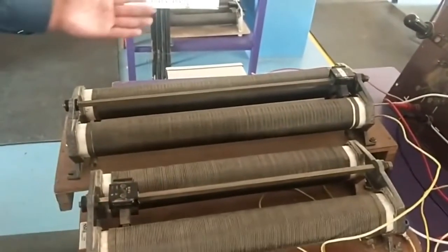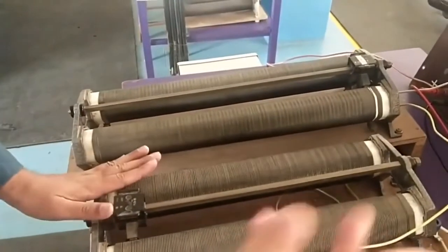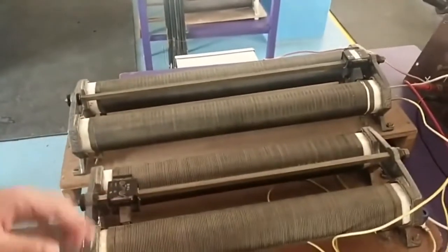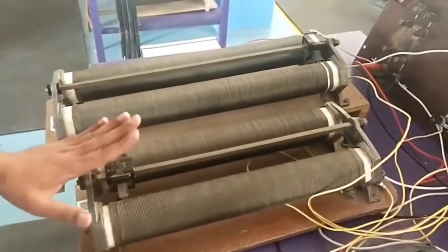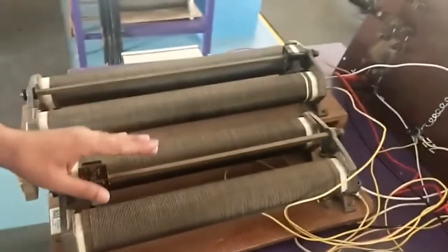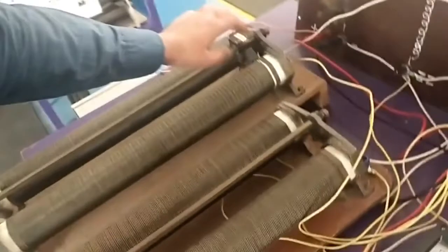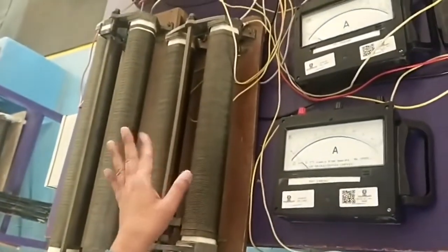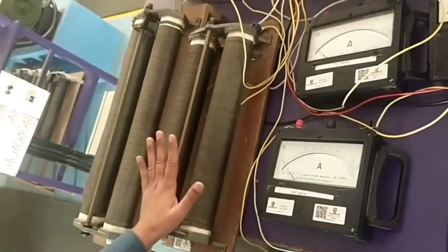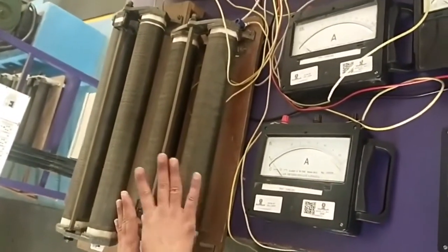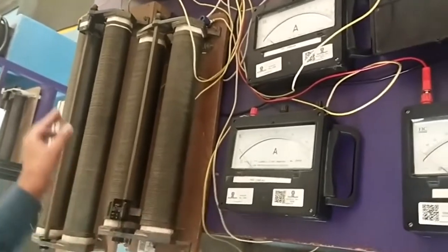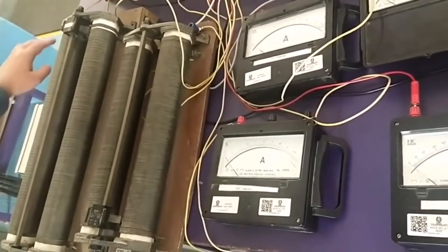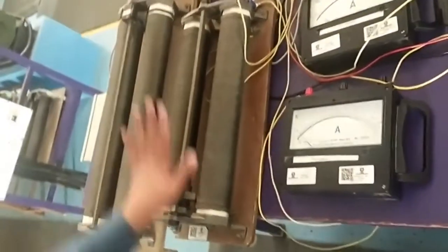And now we are applying the DC supply and check the speed. If it is not rated speed, then we will adjust the armature rheostat to get the rated speed. And if it is not possible, then we will again try the field rheostat to get the rated speed. Once the rated speed is coming, now it is a field control method. So armature circuit is constant. So we are fixing some voltage across the armature and then vary the field rheostat. We will vary the field rheostat with respect to the speed we are cross checking.